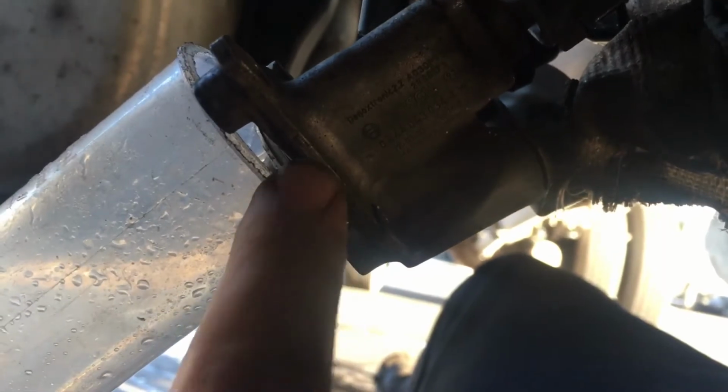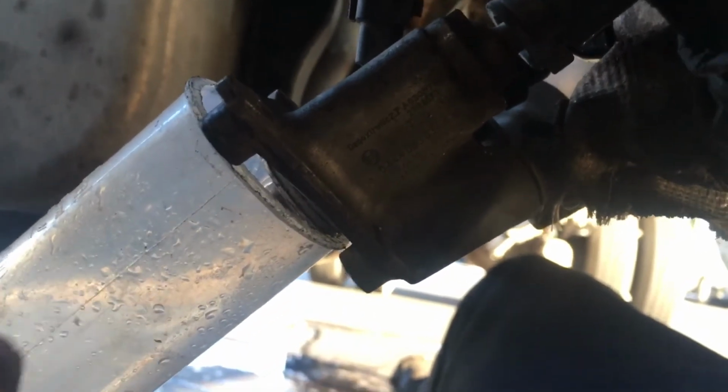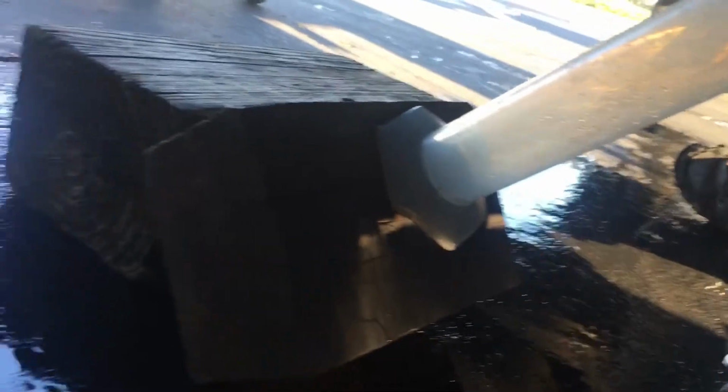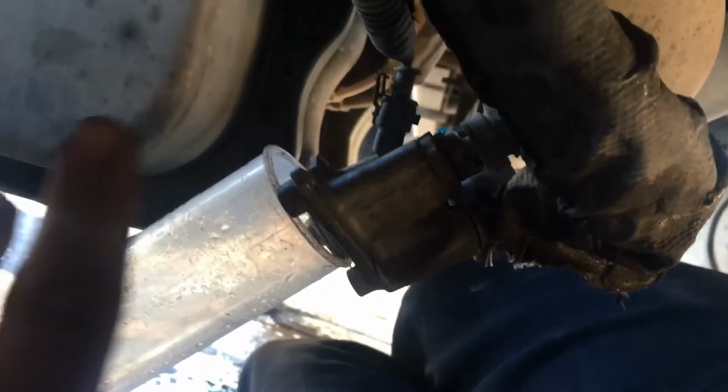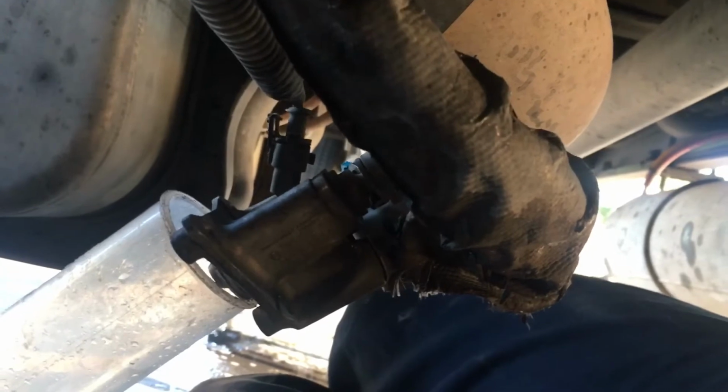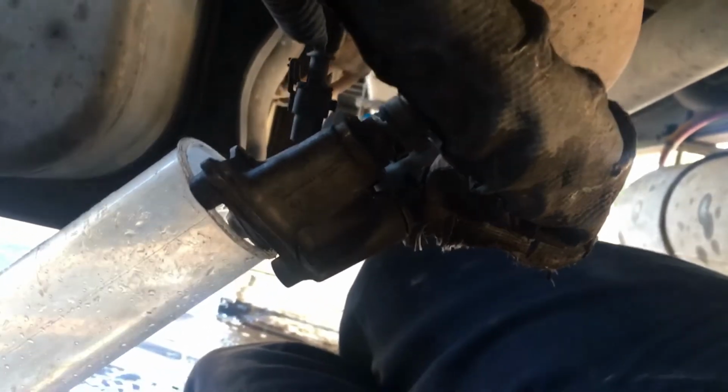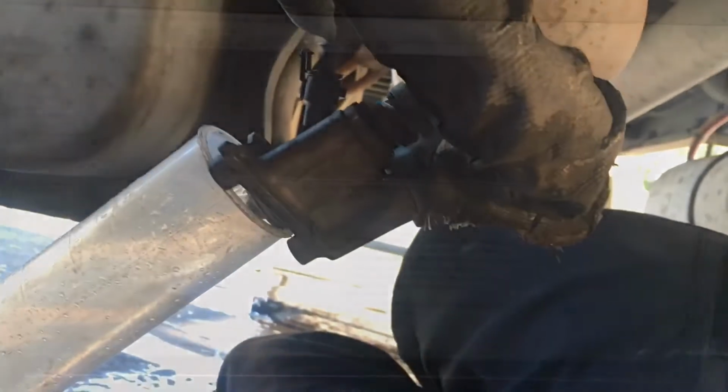So what I've done is I've put the nozzle of the DEF injector inside of my measuring beaker, and I didn't unplug anything else. Just set my beaker up on a couple blocks of wood because this has some pressure because of those lines going on it, and so if you're able to wedge your beaker up in there and hold it in place while you run the test, in order that you collect all the DEF that's being sprayed out of here, so you can measure how much it's putting out. That's the way I do it.